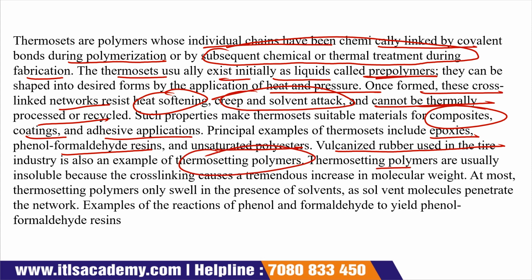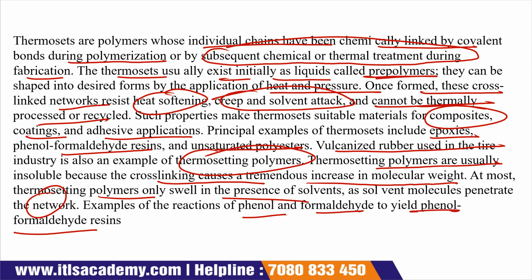Now, thermosetting polymers are usually insoluble because they are cross-linked, which causes a tremendous increase in molecular weight. At most, thermosetting polymers only swell in the presence of a solvent as solvent molecules penetrate the network. For example, phenol formaldehyde resins. Okay, here what happened?